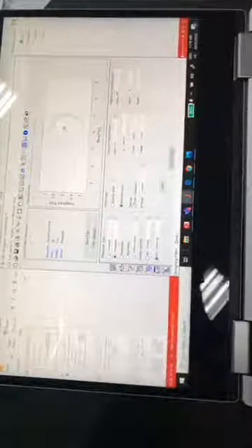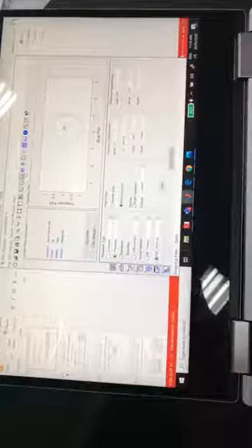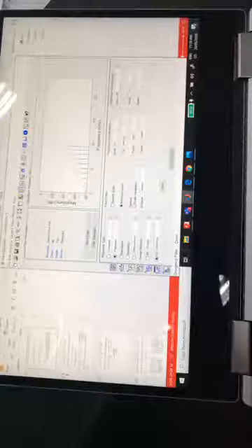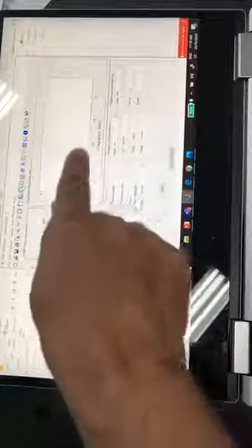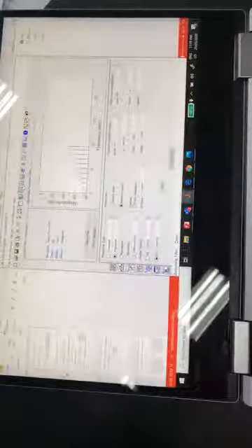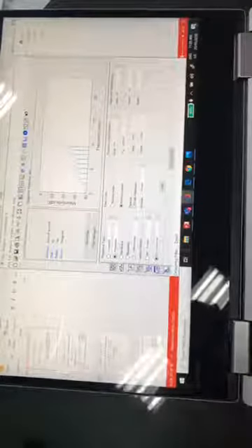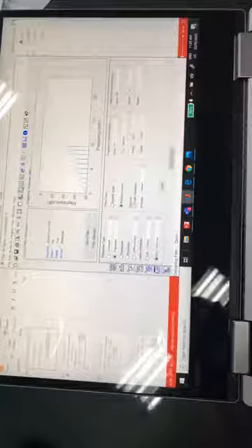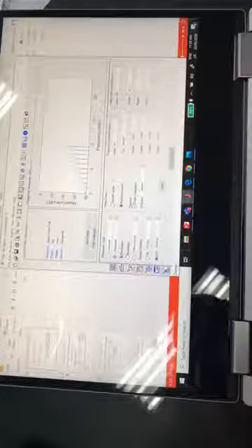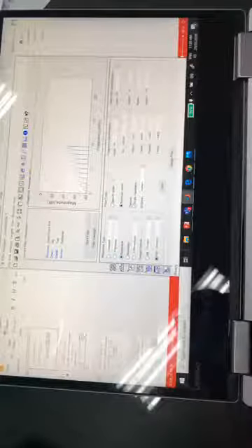If you go and look at the magnitude of the frequency response, you will be able to understand. So the zeros here will make the response go 0, 0, 0, 0, 0, and let pass these frequencies, which are the high frequencies. Okay. So similarly, you can design a band pass.